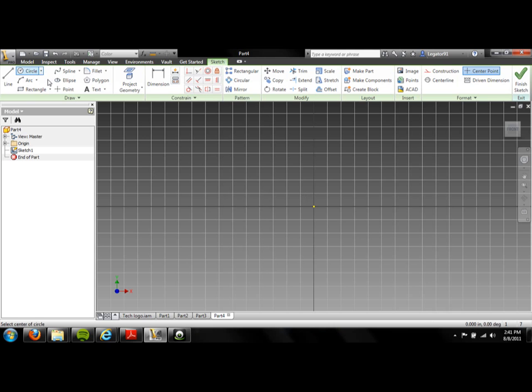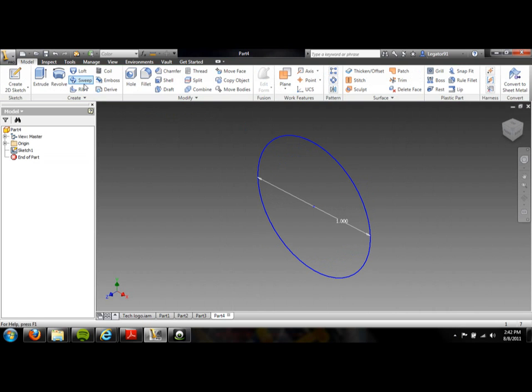So let's just do this. We'll make like a wire, let's say. So we want this pole or wire to be 1 inch in diameter. So this is saying we want to take this circle, just like you would do with Extrude, and we want to extrude it up. But we don't want it to just go straight like it would be a cylinder. We want it to curve. And that's what this feature called sweep does.